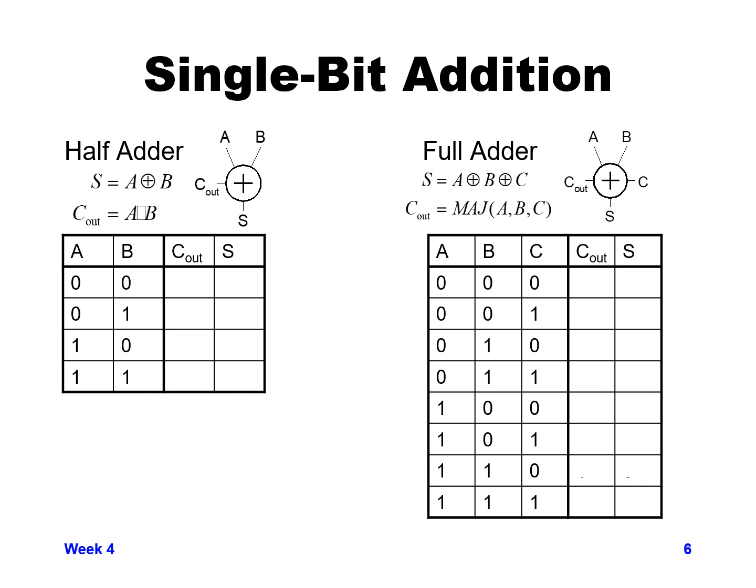So you have four possible combinations of inputs for A and B: 0,0, 0,1, 1,0, and 1,1. And then you have two outputs that we expect. One is the sum of A and B, and the second output is the carry. Depending on what values of A and B you have, you could get a carry coming out of your addition. This goes back to simple addition. So if you have 0,0, you have 0 for your carry and 0 for your sum. Everything's a 0.